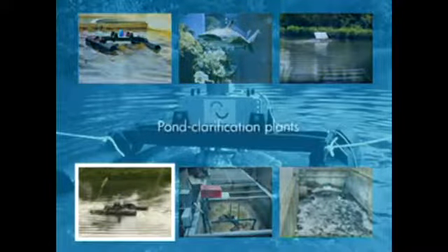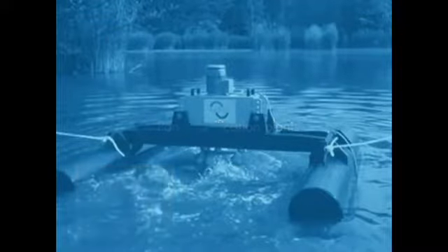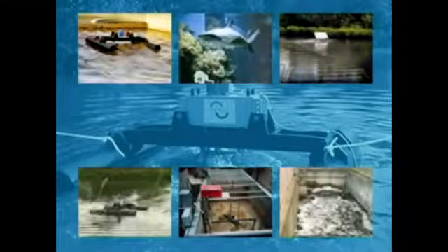Additional advantages become apparent when using OLOID systems for pond clarification plants and in lagoons. On the one hand, the far-reaching flow prevents anaerobic dead zones. On the other hand, the oxygen input is increased via the waves at the pond surface and by improved circulation. Existing aerators may be deactivated either entirely or for specific phases, saving on operational costs.